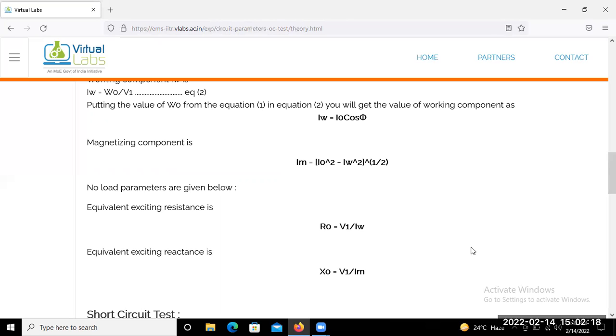And next, suppose you have a 20 kVA transformer. With that 20 kVA transformer, your current rating at the LV side is 20,000 divided by 230. So you may find the LV side and HV side current values from this data. Okay.